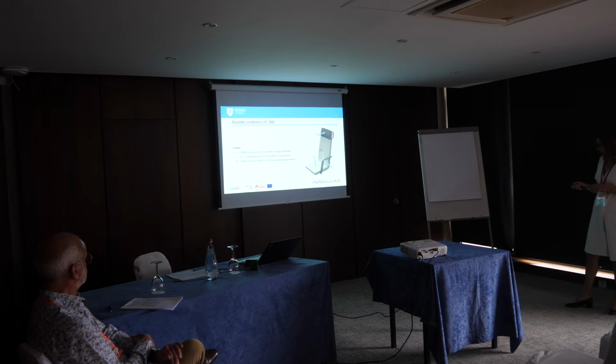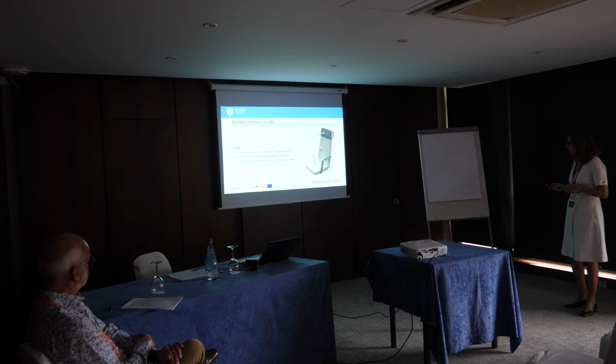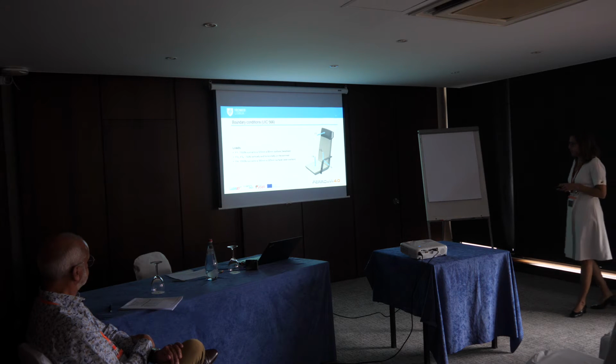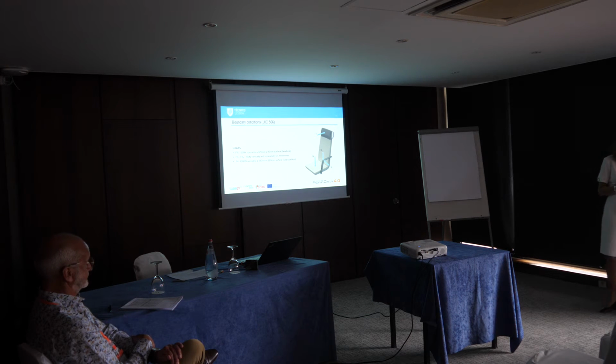Namely, we applied a boundary condition in the headrest, as you can see here, with a total value of 1500 newtons, normal to the surface. We have applied also a vertical load in the armrest, a horizontal load in the armrest also, and we apply a distributed load in the seat function, as you can see here, with a total of 1000 newtons.